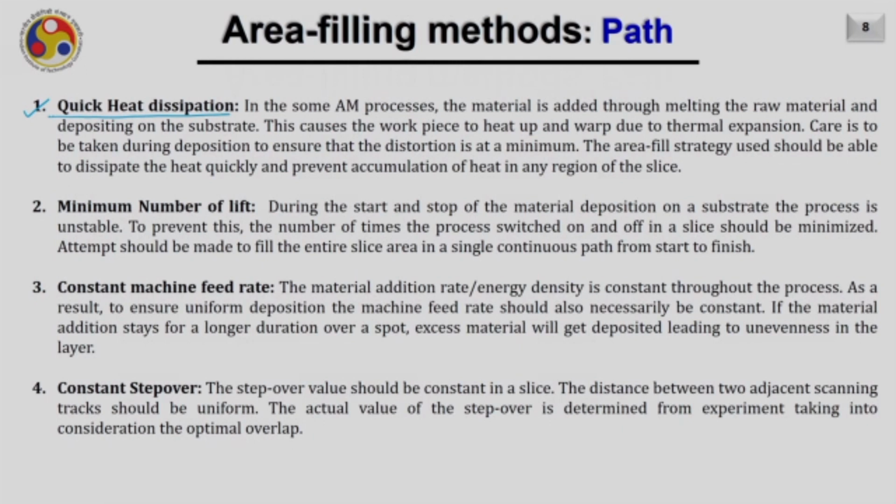In some additive manufacturing processes, the material is added by melting the raw material and depositing on the substrate. This causes the workpiece to heat up and warp due to thermal expansion. Therefore, care is to be taken during depositing to ensure that the distortion is at a minimum. Therefore, the area filling strategy used should be able to dissipate heat quickly and prevent accumulation of heat in any region of the slice.